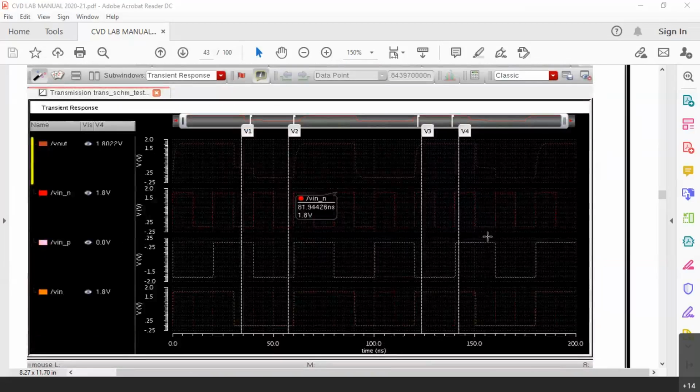You can find the differences between the two waveforms. Anyhow, I am showing you the waveform here, where you can see a small difference. The lowermost one is Vin, and there are two pulses, Vin N and Vin P. NMOS and PMOS are accordingly turned on. Let us say NMOS is turned on here, and at that time PMOS is also turned on, because the PMOS gate is 0 and the NMOS gate is 1. That means logic 1 is transmitted to the output.